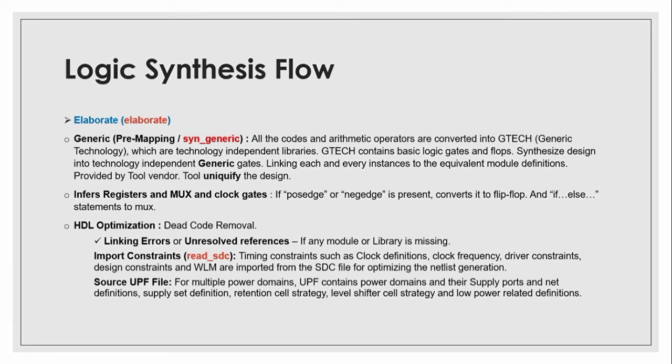The design may be slower than expected, because if you are not mentioning the maximum delay, it will obviously be slower than expected. That means performance-wise it is failing. The design may consume more power than expected if you are not properly mentioning the power constraints. And again, the design may be less reliable. That's why we prefer to have a constraint file as a compulsory input for the synthesis tool.